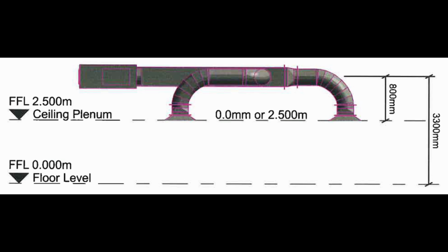Visibility control. Sometimes, after placing a component, Revit warns that the element is not visible. This usually happens because the element is above or below the view range, the view discipline hides that category, or visibility/graphics overrides are turned off for that category. Using VG or VV allows you to toggle categories like electrical fixtures, mechanical equipment, or plumbing fixtures back on.